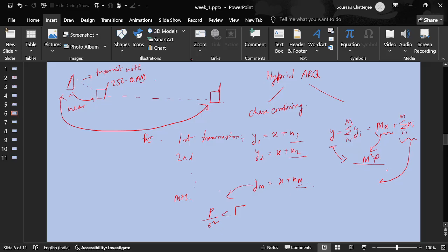Noise is usually independent because you are receiving at different instants. So the noises are going to be independent, and since they are additive Gaussian, what is their sum power going to be? M square sigma square or m sigma square? M sigma square, because they are going to add linearly since they are independent. So your SNR is now becoming MP over sigma square.